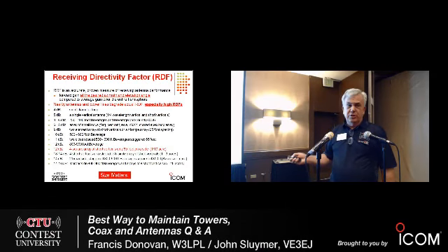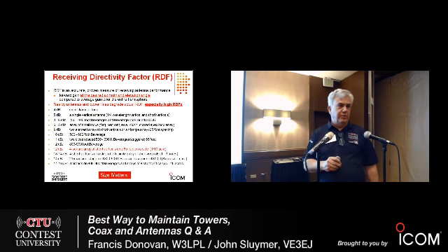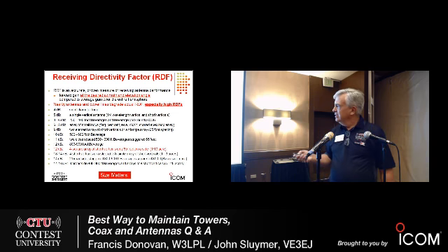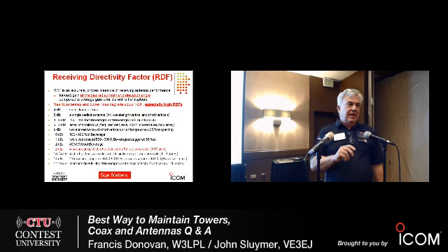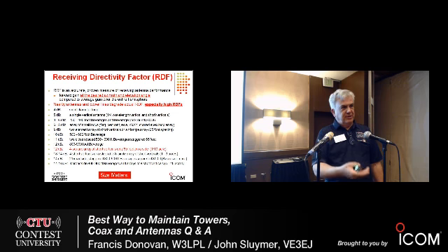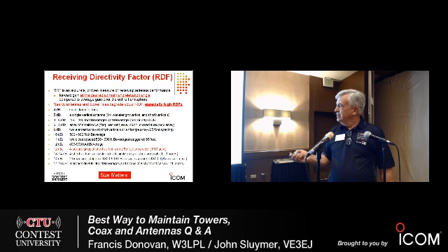The next step up is also a pretty simple antenna. It's 2 short verticals, and I'll show you how to build those verticals later in the presentation. They're separated 65 feet apart. They're 25 feet high, so they're quite small. Even if you don't have a piece of land you can permanently put one on, you can install an array of 2 verticals in about 4 hours. And then take it down when you're done with it. So for a DXpedition or a contest weekend, you can easily install it and remove it. And I'll show you how to do that.